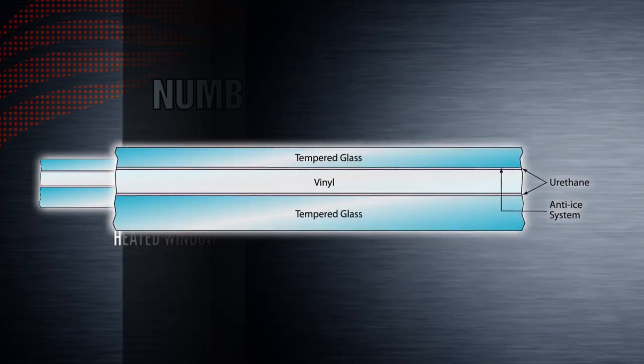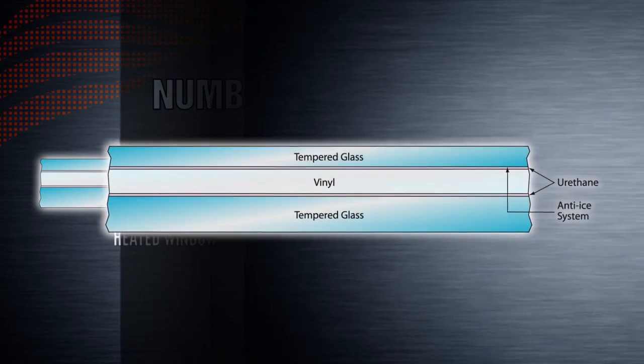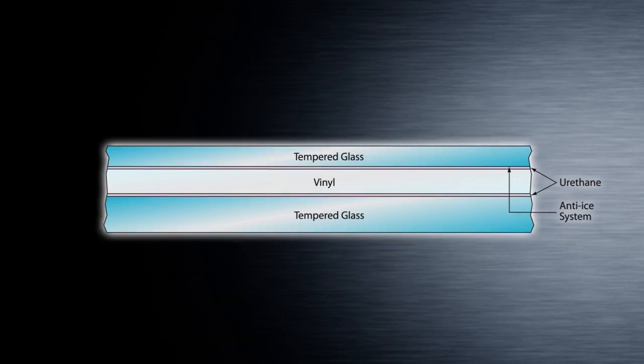Flight deck windows numbers 1, 2, 3, 4, and 5 consist of glass panes laminated to each side of a vinyl core. The inner glass pane is the thicker and carries most of the structural load. The vinyl core is a backup load-carrying member, and it prevents the shatter of broken glass if the inner pane breaks.